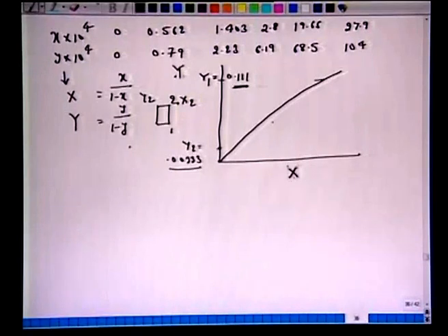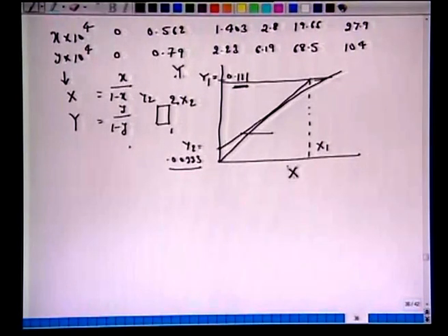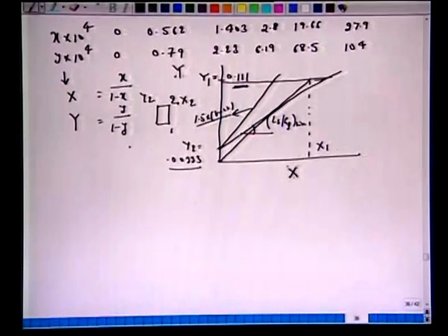Okay. Now, if we realize that there is a pinch here, we can draw this curve as a tangent. So, wherever it makes a tangent, from there we can get either x1, all right, or we can take the slope as Ls by Gs min. So, whichever way you think is comfortable, you find the slope and then take 1.5 times. The slope would be 1.5 times the minimum, all right. Or you can write down the expressions for this operating curve, and then you can obtain the Ls by Gs operating curve. So, either way it should work.